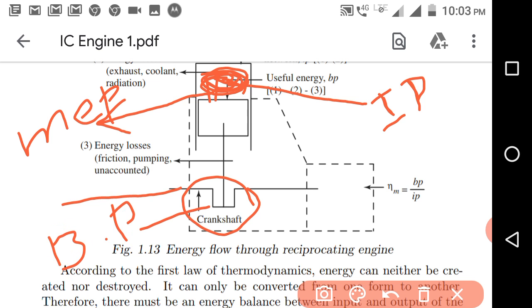This power is produced in the expansion process, where the gas expands and puts pressure on the piston throughout the expansion process. So the intensity of pressure varies throughout the expansion cycle. We cannot say there is maximum power when the piston is at TDC and less power when the piston is at BDC. So we take the mean pressure, and we call that the mean effective pressure.